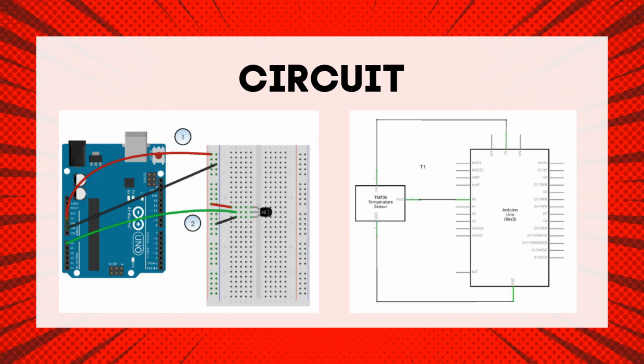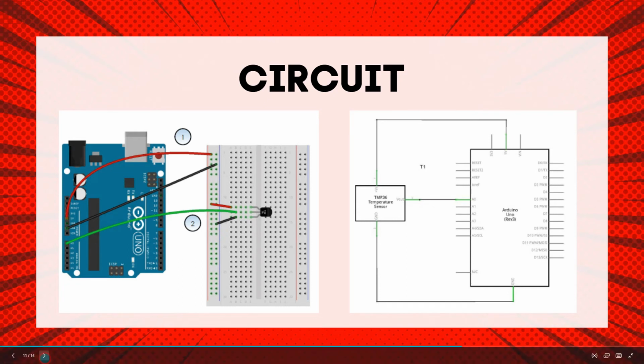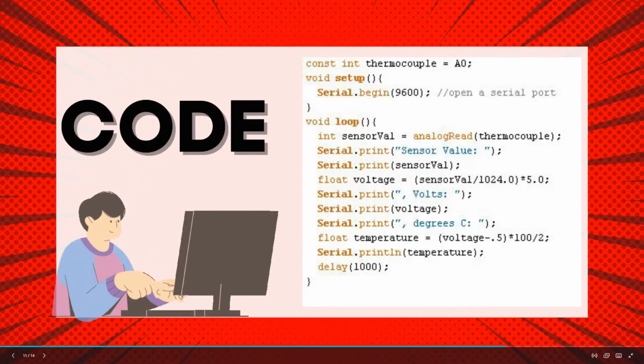The output pin should be connected to the A0 pin of the Arduino, and make sure that these connections are strictly followed. If you are already done with the connection or setting up the breadboard and the wires, and our Arduino Uno is also connected, let's proceed to coding.